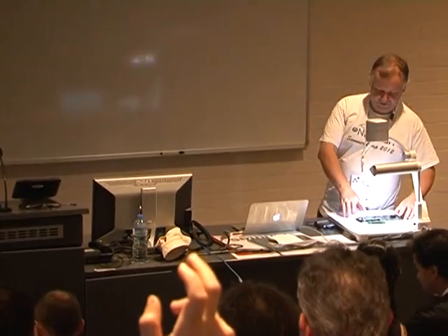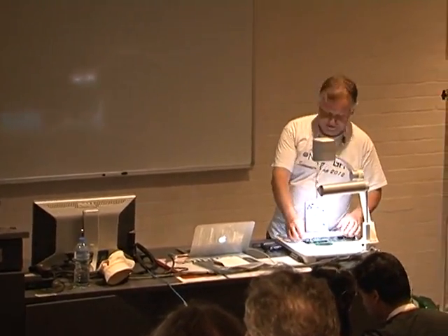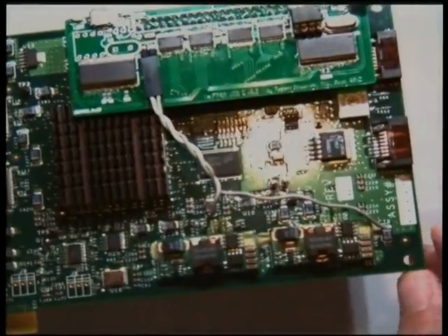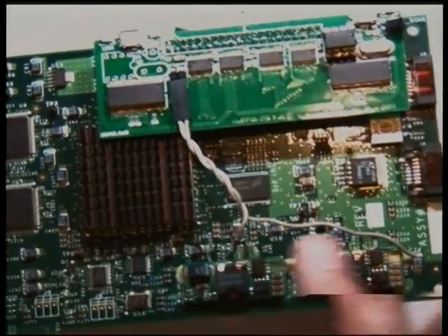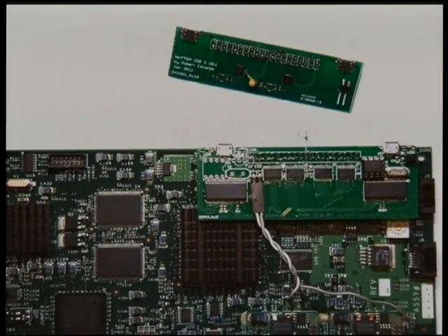These are the wires that were being referred to, by the way. They're connected to 2 points on the board where there's 2.5 and 3.3 volts power. So all the switching is in the FPGA. It's not Open vSwitch or any of that sort of stuff. This is all written from scratch in Verilog.